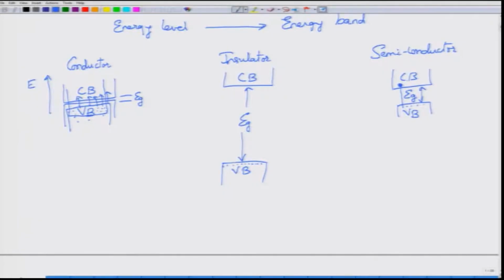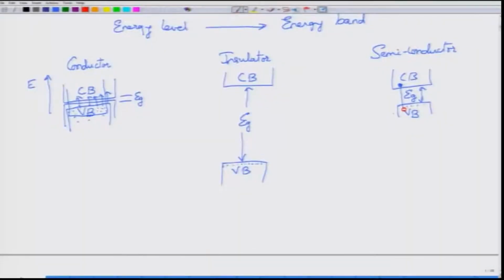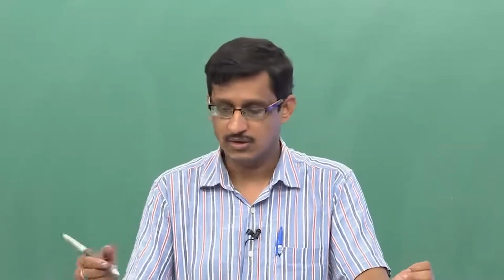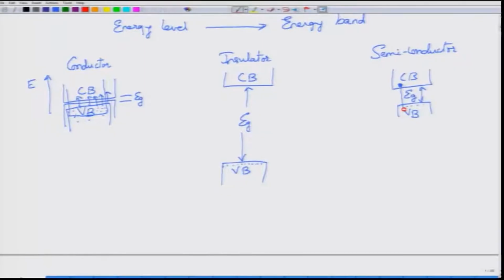As the electron jumps, it leaves behind an empty space. The actual phenomenon is very deeply mathematical and deeply physical, but this simple picture should be enough for us. In this simple picture, whenever an electron leaves the valence band, it leaves behind a hole. This promotion from valence band to conduction band can happen by an external electric field. It is not necessary that you always have to apply a photon to induce this transition. This transition can happen by an external current being forced or something like that. So, this is called a hole, and whatever is actually here is an electron.